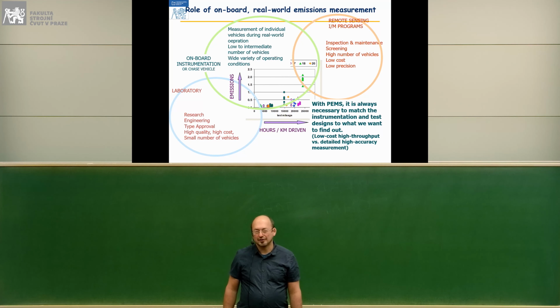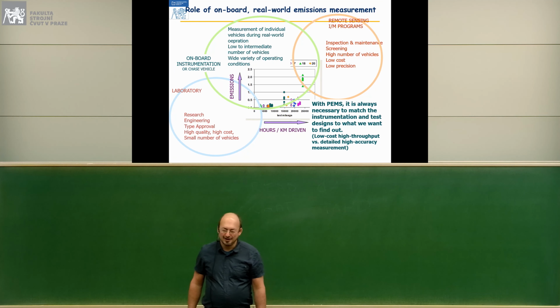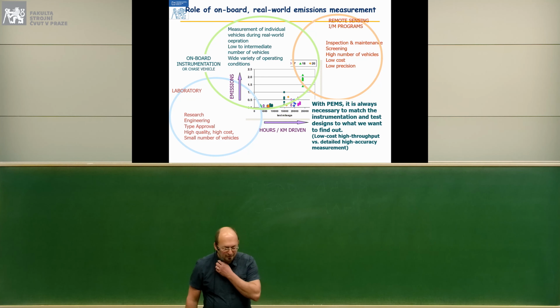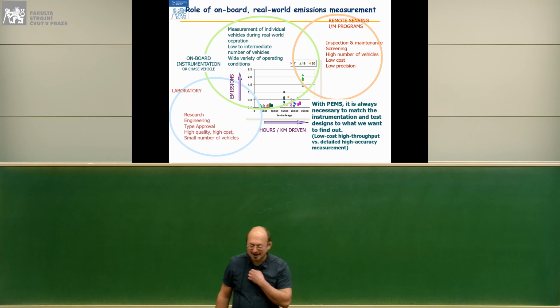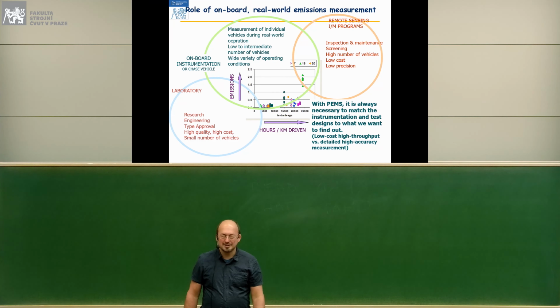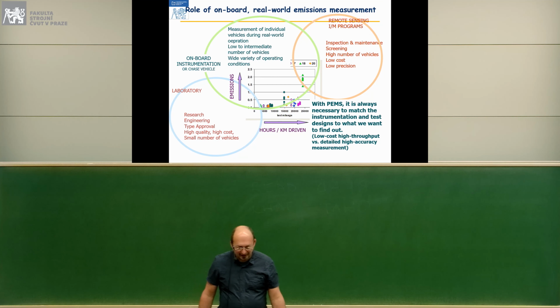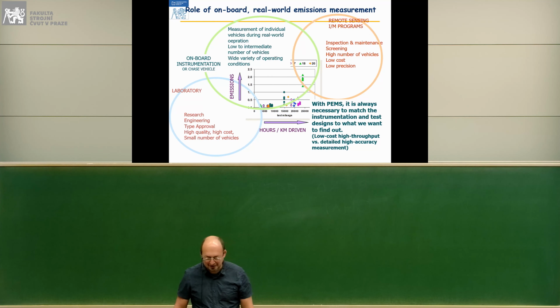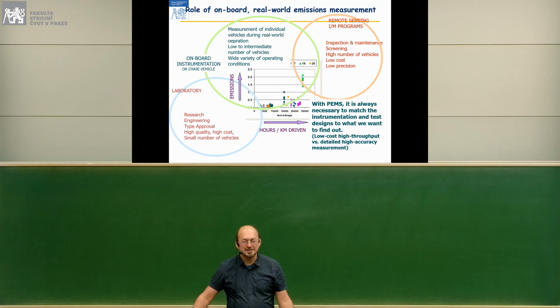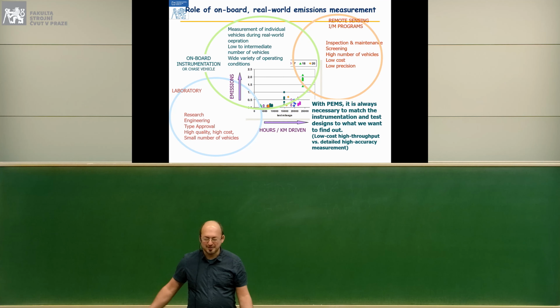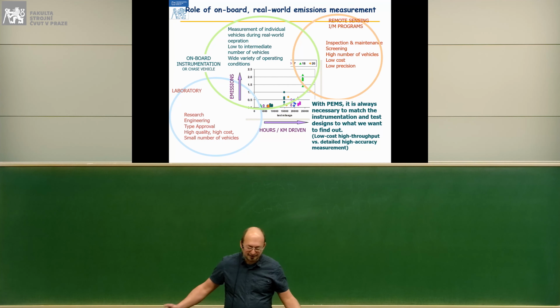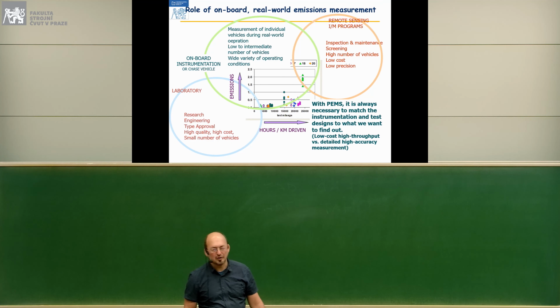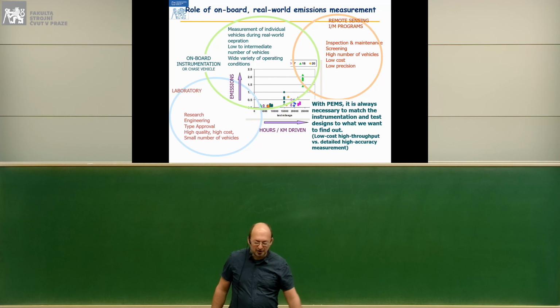Then we have type approval tests to ensure that a vehicle that we would like to sell in Europe or the United States or India or elsewhere in the world meets some emission standards. And because some manufacturers are satisfied with the vehicle meeting the emission standards in a laboratory, and who cares about what happens in the real world, the type approval legislation is expanding to the whole vehicle life and also to realistic driving conditions where we get real driving emissions.